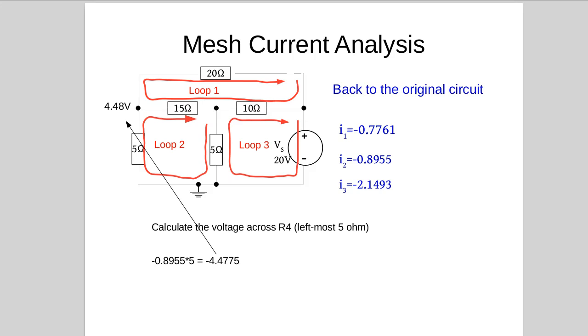Let's try and work this one out. Now in this case, again, I3 does not flow in the direction of the arrow. The answer was negative, so I3 flows this way, and I2 flows this way. I2 is flowing up, I3 is flowing down, and I3 is bigger, so the resultant current will be flowing in at the top, so the top will be positive. And it works out to 6.27 volts. That's the voltage calculated with node voltage analysis.